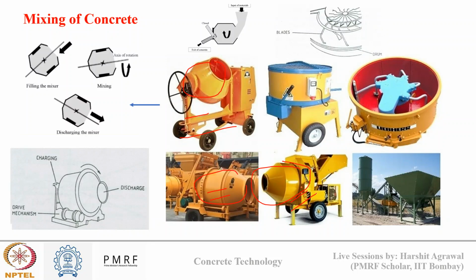So in the tilting drum mixer, what happens? The drum will discharge concrete by tilting downwards. It has the ability of rapid discharge, and it is often used for large scale projects. Generally we use low workable concrete with a higher aggregate grade in this mixer, because a more workable mix may encounter the problem of segregation.